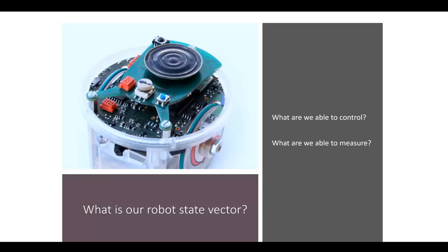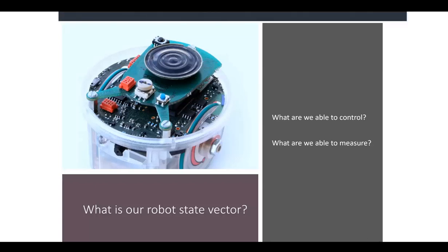So we can control the rotational speed of the wheel. That's true, right? But basically what we're doing is we're controlling the position of the motor. So we can figure out how far a motor has rotated by using an encoder on it, and that'll just tell us what the joint angle is. It just happens to be that these are continuous joints, so we're able to rotate it continuously. So to figure out where epoch is, we're going to need X, Y, and theta, right? We need to know the X and Y coordinate for the robot, and we need to know its orientation.